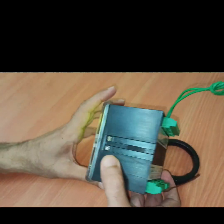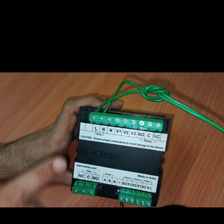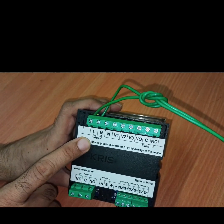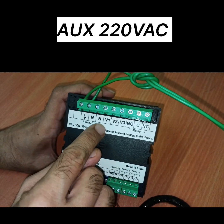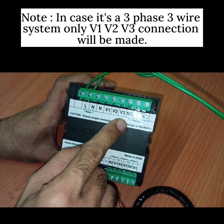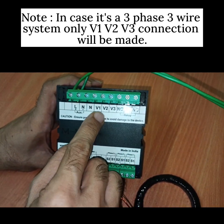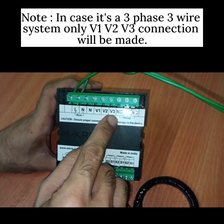So as usual, first we will have a look at the connection diagram. We look at the back side of the relay and we can see that auxiliary supply is on the top left. Here all the three voltages along with the neutral connection will be connected. In case it's a three-phase three-wire system, only V1, V2, V3 connections will be made.